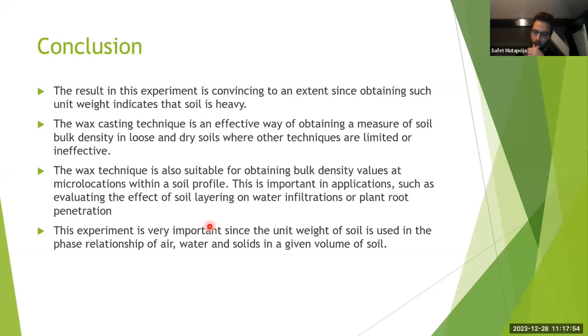At this moment, I'm working on a huge embankment. It's 45 meters in height, and we always have trucks there. Our design requirement was 30 megapascals of the modulus, and we got more than 100 just because we had trucks all over it. So you cannot overcompact it. That's basically impossible, because everything above design compaction is good; it's better to have more compaction than less.